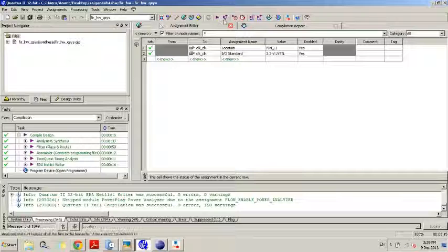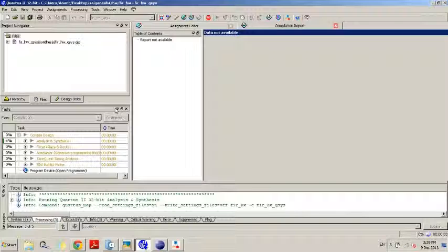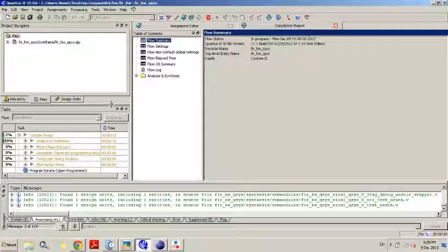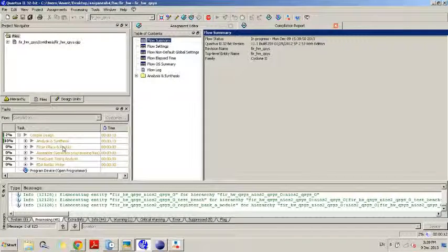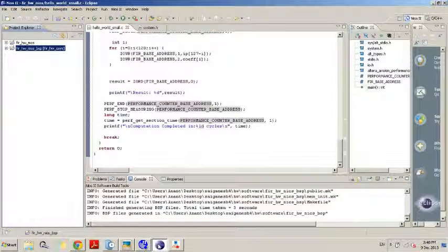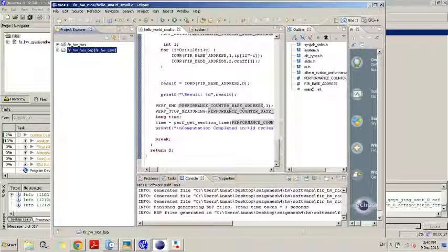We'll simultaneously keep an eye on the project progress. Now you go to Nios SBT, you won't be seeing these two files present. Before you arrive at this screen, you have to select the workspace. The workspace by default should be under the project directory. You can create another separate directory, naming it hardware, since this is a hardware approach. After that, go to File, Alt-Shift-N, that is, create a new Nios II application from BSP template.